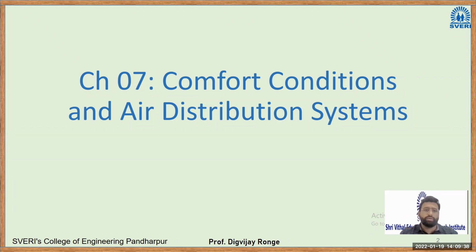So first we will calculate the heating and cooling load acting on the building. Then you will select the air conditioning system. After selecting it, you will prepare a bill of material, purchase the equipment, etc. Now the last step is to supply the air. You have to install the system, and along with it you also have to install the ducts and other components in the building.